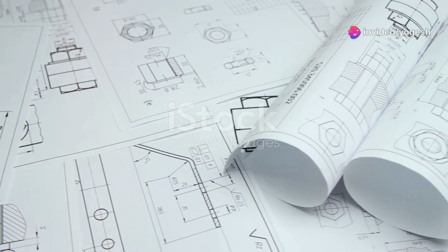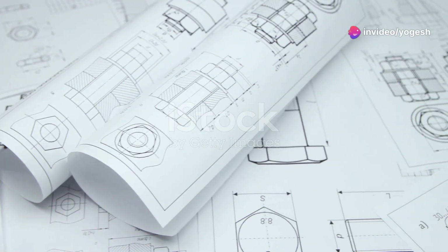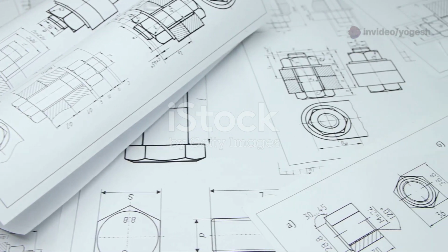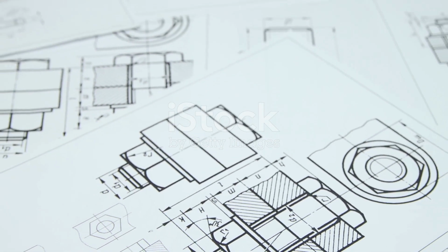Group notes together and keep leader lines clean. Avoid crossing dimensions or letting annotations overlap. Organized notes make your drawing more professional and much easier to follow.